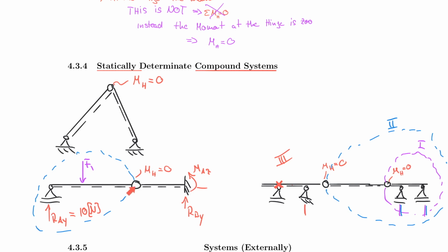Again, I see students often initially being confused by the hinge here, but the trick is, once you've figured out one unknown, the hinge does not matter for now. At least as long as we talk about support reactions. Later on, when we talk about internal forces, of course it has an impact. But again, we'll talk more about that later. So for now, don't worry about this. You find your subsystems, you find the side that you can solve easier. So for example, the right subsystem here, you could have not solved that.